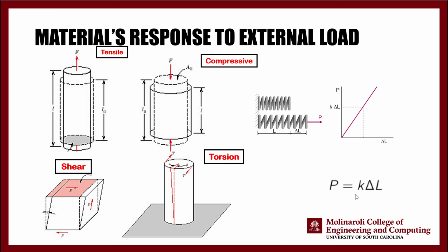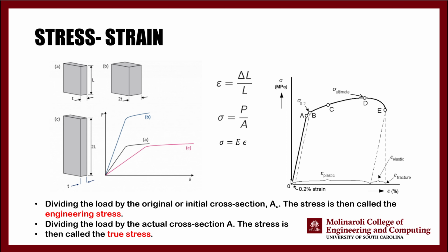These two are equal to each other when you multiply the change of length, elongation, by the spring constant. So whatever we do here, and in general in the mechanics of materials, in the elastic region, is going to be based on Hooke's law for springs.